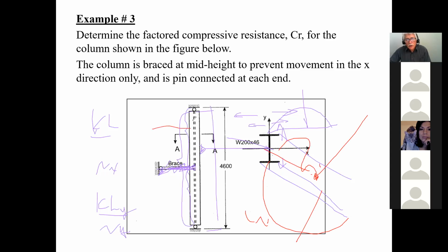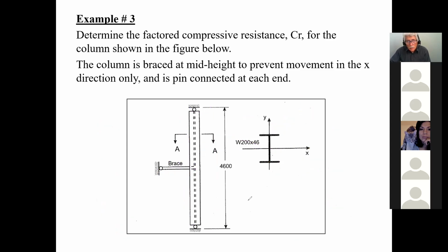And if I would have two of them, then it's going to buckle... Okay, I got it. Exactly. In other words, it can still govern, but at least you know that it's got half the length that's going to buckle, as if I divided the column into two. The brace is acting like a flange, buckling it. The brace is telling the column, I'm going to hold you here, but I'm only holding you in one direction, which is the y direction. It's the y-axis that is not moving out of its plane. The x can still be free to go any way it wants.